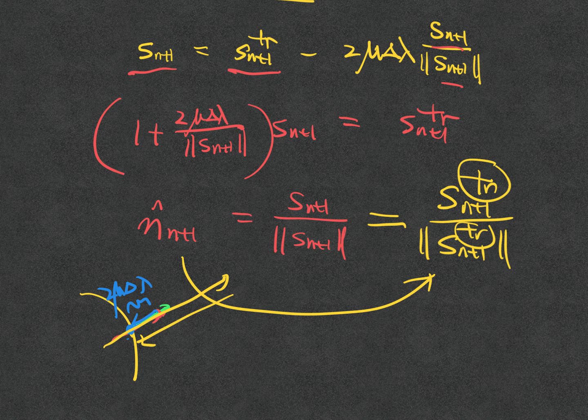What I did not do is go here or here, because that would imply a change of direction between the trial stress and the actual stress, right? The directional part of that never changed. I'm just changing the magnitude. Initially I'm overshooting, and then I'm using that direction as a template. I only correct it by adjusting the magnitude so that I can hit back onto the yield surface. So this is actually a very important trick to make the prediction much easier, because then I don't actually need to predict n.